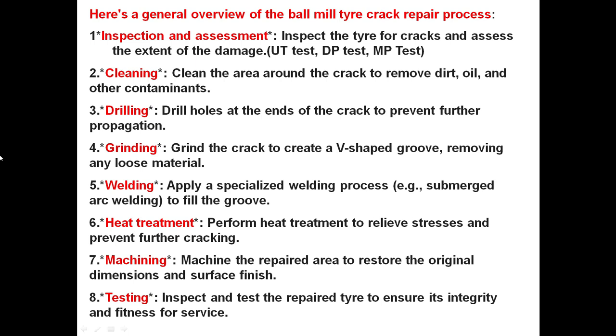Grinding: grind the crack to create a V-shaped groove, removing any loose material. Fifth point, welding: apply a specialized welding process, for example submerged arc welding, to fill the groove. Heat treatment: perform heat treatment to relieve stresses and prevent further cracking. Machining: machine the repaired area to restore the original dimensions and surface finish. Testing: inspect and test the repaired tire to ensure its integrity and fitness for service.